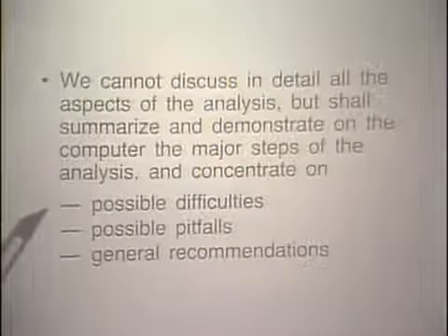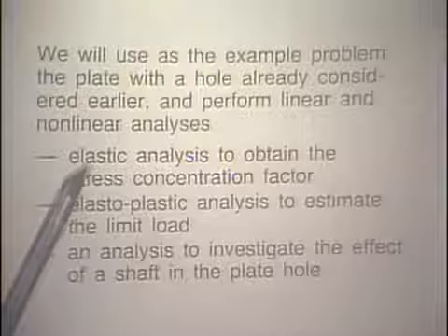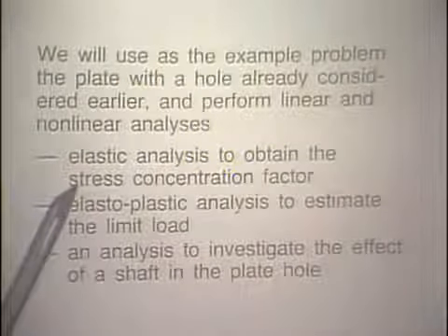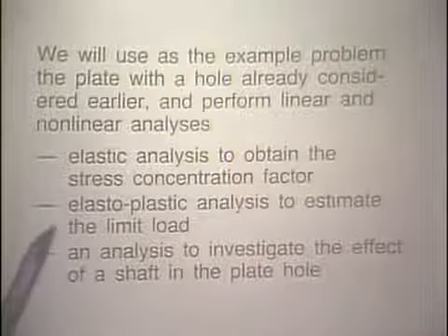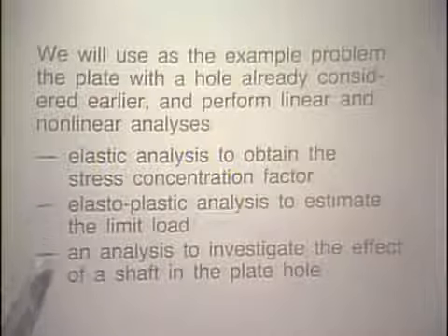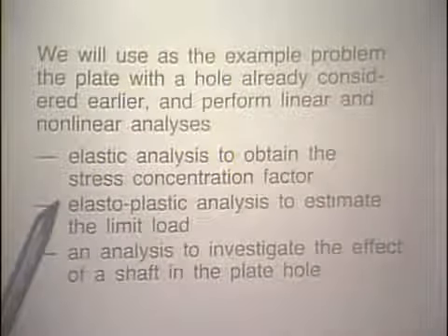As the example problem, we want to use the plate with a hole that we already considered earlier, and we perform a linear analysis and then a nonlinear analysis. Remember, I pointed out in the previous lectures that it is very important to always do a linear analysis first before you go into a nonlinear analysis. The elastic analysis is performed to obtain the stress concentration factor at the hole. Then we do an elastoplastic analysis to estimate the limit load, and an analysis also to investigate the effect of a shaft in the plate hole. These two analyses are being performed in the last lecture of the video course.